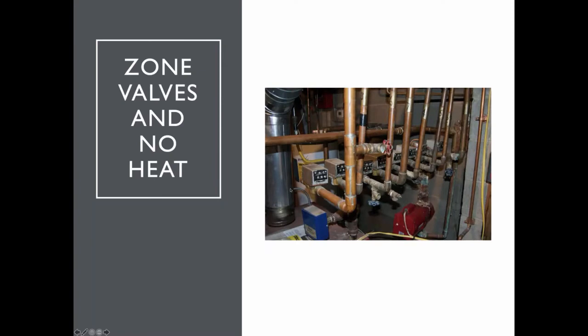This one was a real head scratcher. We got there, it was a Friday night, a cold night, and they said, we have one apartment without heat. And by the time I got there, they had turned the heat up to 210 degrees in the hydronic loop. It would scald your hands just holding the pipe.